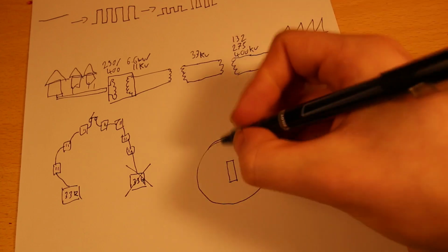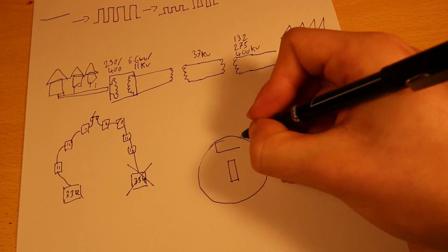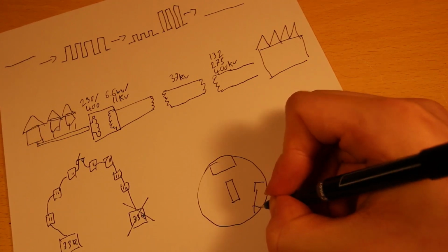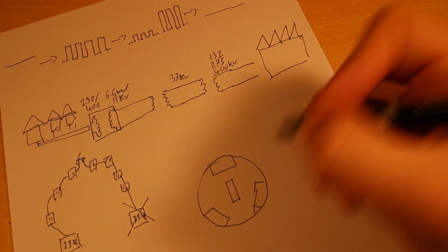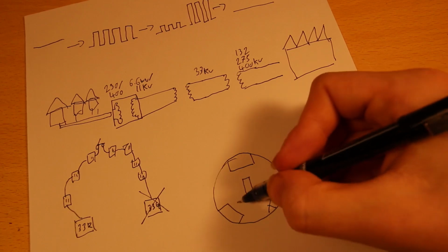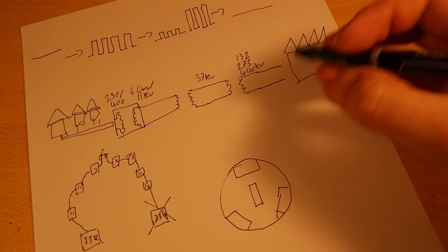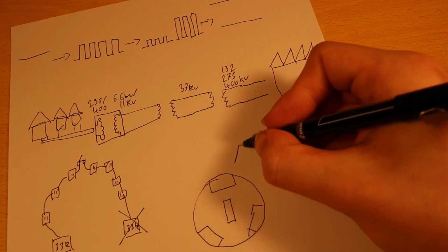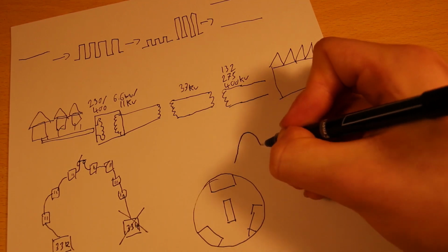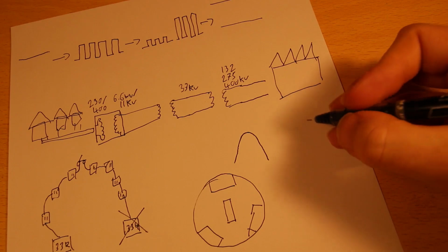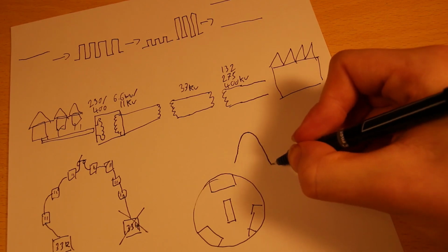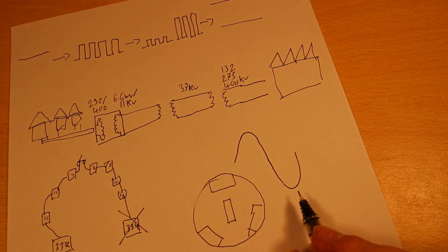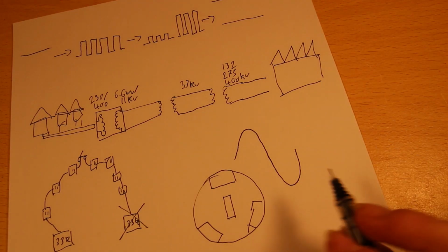And the way they do that, they have coils of wire, usually 3 of them. I'll explain that in a second. Here, like this. So as the magnet spins round, the voltage induced in that wire will go like this. It'll go up, and then as the magnet passes, it'll go back down again. And then as the other pole of the magnet comes, it will go up and back down again the other way. And doesn't that look a bit familiar to what I just showed you on the scope?